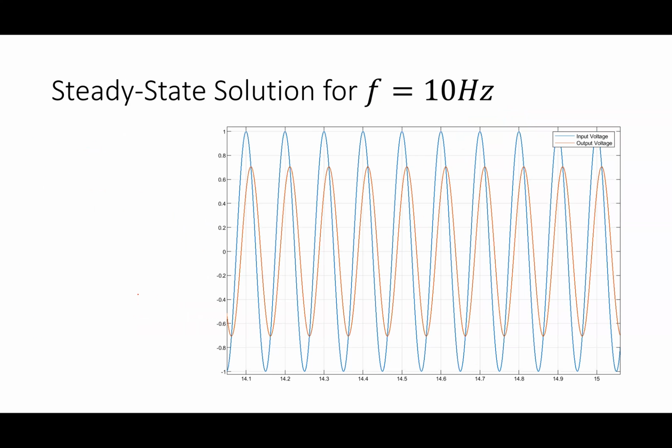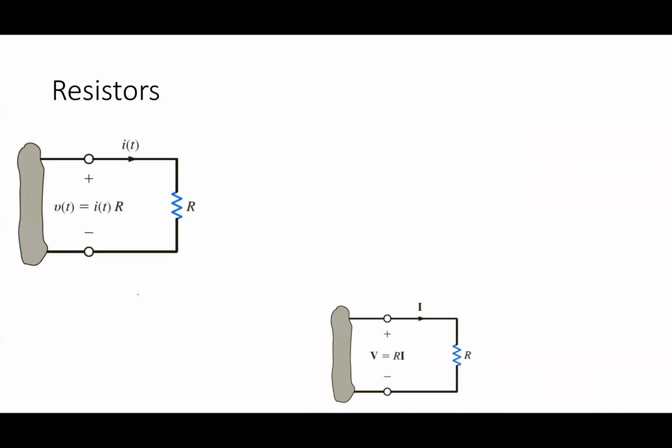So we talked through this here. Now I want to get to the why of this. Let's look at how we would analyze a circuit. Let's say I have a voltage source across this resistor. My voltage source was V cosine omega t plus phi. I gave you that circuit. What would i of t be? V of t divided by R. Yeah, V of t divided by R.